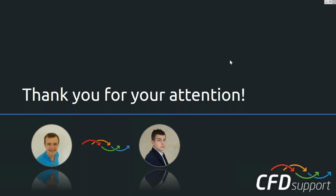But you can get these values after the simulation. First you simulate, then you see, okay, I'm in the correct range, that's okay. If not, I have to refine the mesh, for example, make it coarser or make it finer, and use a different approach for wall treatment. So there are many applications for which y plus is important. Hope that helps. Okay, thank you, Radek.